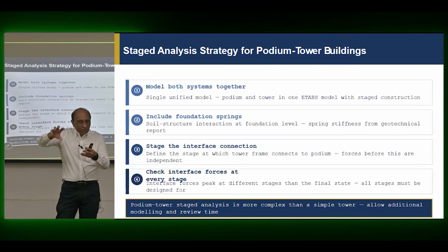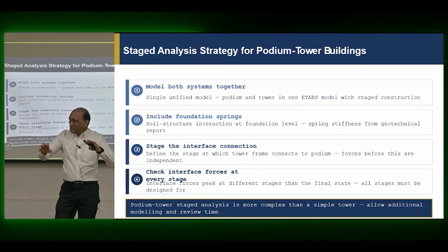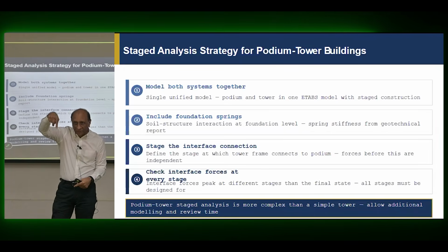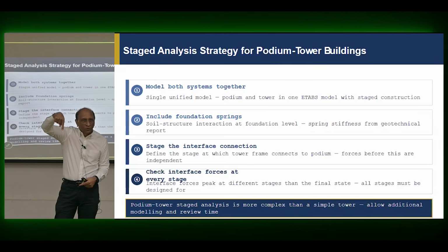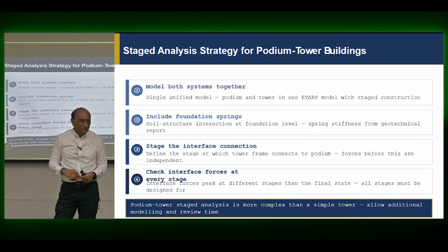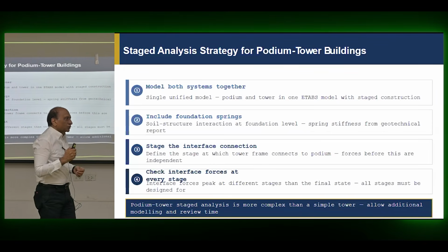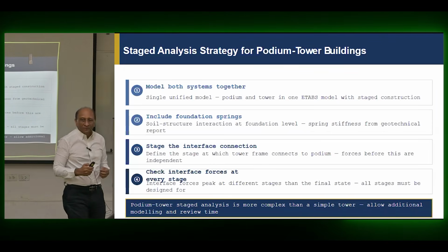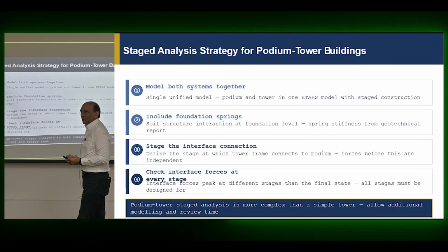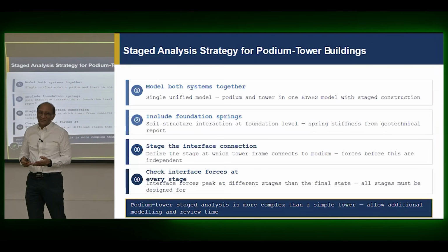Get the overall total forces first, and then apply them. If I was doing that at that time, I would just draw it and put those point loads and bending moment forces on this system, check the system first, then gradually add more and more. So please remember to simplify the problem, understand the mechanism, and only then move to ETABS modeling of 6 towers together.